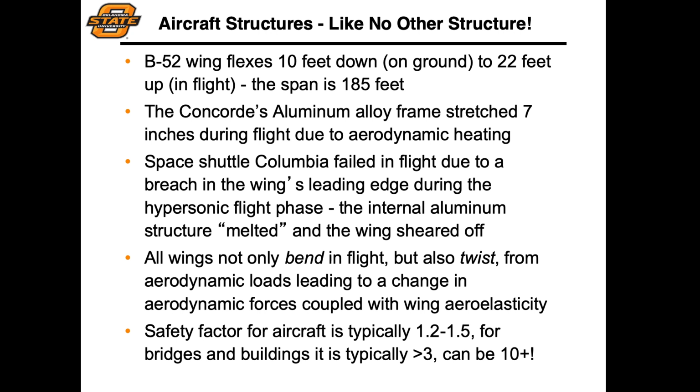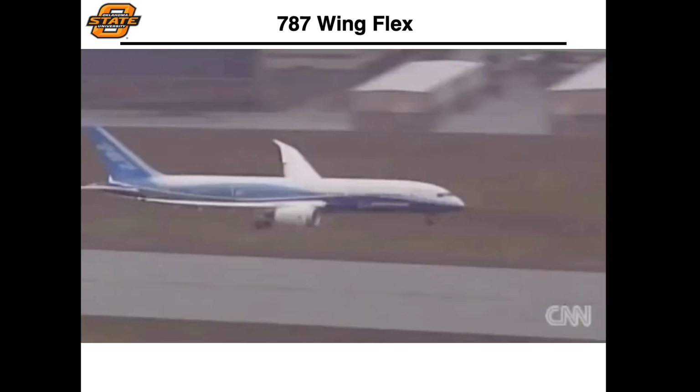Sometimes really an order of magnitude greater than the design load. But for an aircraft, however, you'll typically see that your safety factors are on the order of about 1.2 to 1.5 of the maximum design loads that you expect to see in flight. So you have a relatively small margin of, say, 25% to 50% where you might see some failure in some component of your aircraft due to structural limitations.